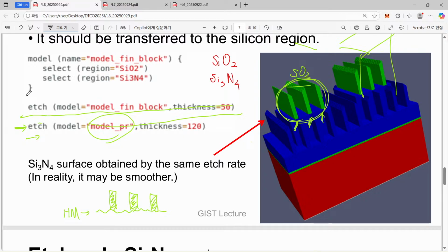So my suggestion is don't be too ambitious on this code. This code has many disadvantages. One is if you give it a long name, then it does not complain. It's silently neglected. One example is here we have a thickness, but if you misspell thickness, then silently it neglects it, and thickness is taken as its default value, just number 1.